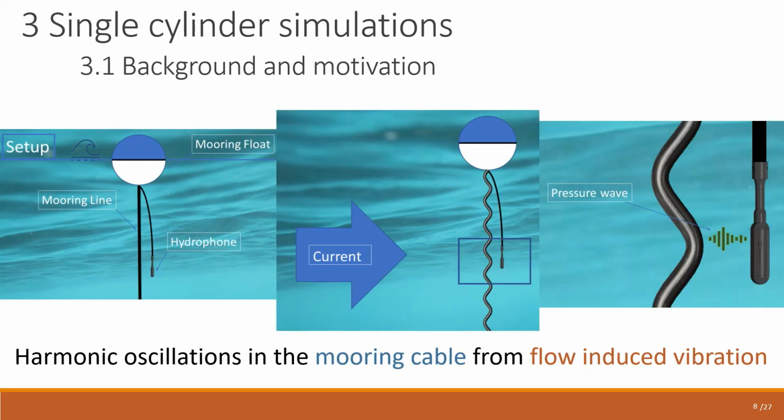How does a vibrating mooring line create sound? Well, when a current passes by a mooring line in tension, there is the potential for vortices to be generated, which can lead to an oscillating lift force on the line. The vortices are actually low pressure regions that travel downstream. The pressure waves can be picked up by the hydrophone as sound. If the sound is in the acoustic range of rainfall, this can be a source of acoustic interference.